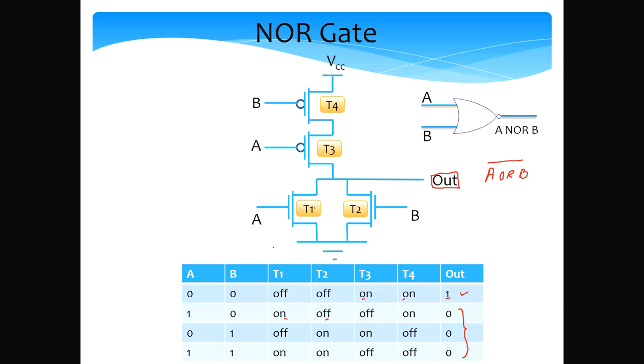But what we have over here for the second input is that the transistor T1 is conducting, so the output terminal is directly connected to ground. Because this transistor T1 is conducting, essentially we can add a straight line over here showing that it is directly connected to ground. As a result, the voltage at the output terminal is equal to the ground voltage, which is 0, and thus the output is a logical 0.